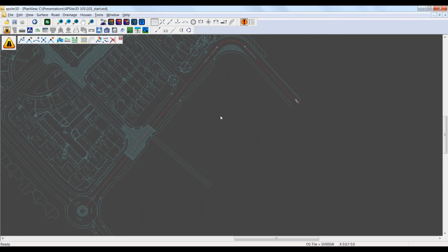Now the top tip, the advice for creating center lines, is to use as little snap as possible. So I just snap to 3 locations: snap to the start, snap to that arc, and then snap to the end. And as I said before, a theme that I'll be returning to again and again is the fact that I can now edit this. So if I wanted to create another point along that line, I can enter its coordinates or do it graphically. If I create a point, once I've created it, I can then move it around, or if I'm not happy with it, I can then delete it.